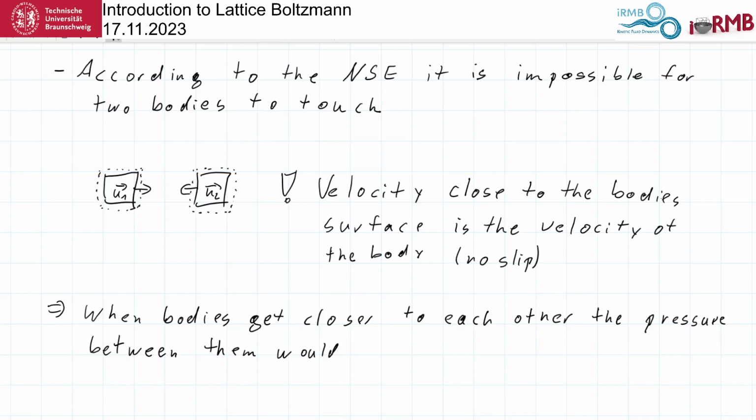It has no physical bound. It can go to minus infinity, and then the force will be minus infinity. Now, if you think about what pressure actually is, you should know that pressure cannot go to minus infinity, because if everything is removed, if there is a vacuum, this is the minimum pressure that you could have. And so actually this force would be finite instead of infinite, as implied by the Navier-Stokes equation.